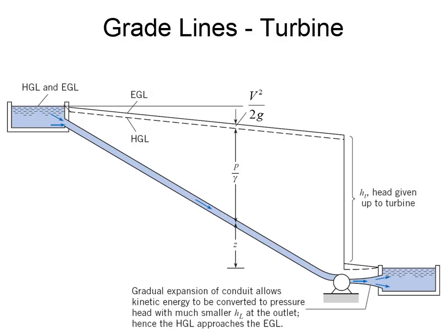So when I say that a pump doesn't increase the velocity, what I mean is that between A and B, upstream of the pump versus downstream of the pump, isn't changing the velocity in the pipe, but the pump can change the velocity compared to if there was no pump. That is why the velocity doesn't change inside of the pipe.